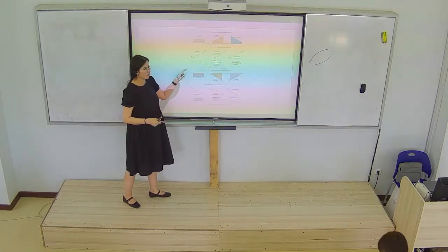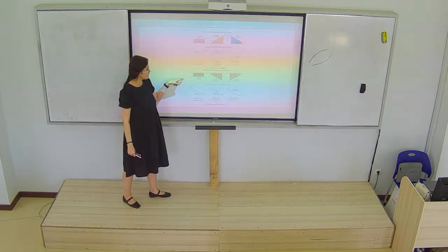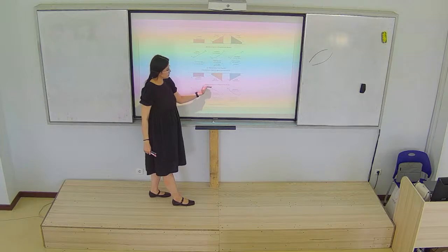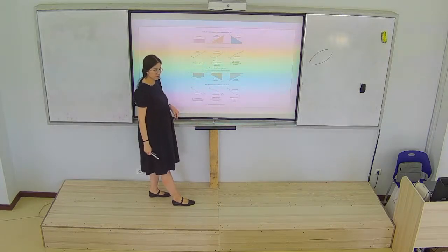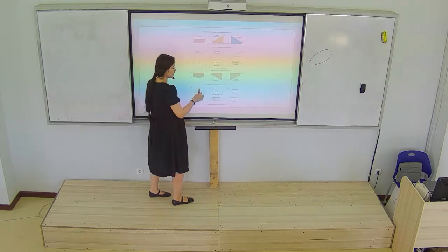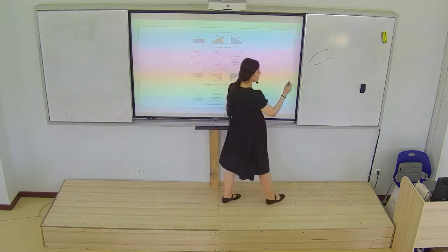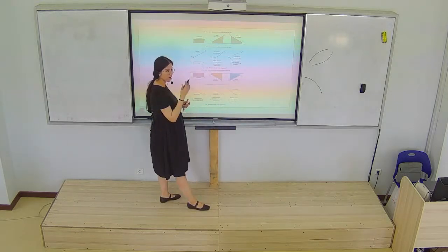So, if our shear force diagram is on the minus side, it means that our moment will decrease. Like that. And if it is decreasing more, the moment will be the opposite of this one. This one is the plus side, this one is the minus side. If it's getting more negative, your slope will always be like that. Did you understand? More negative.